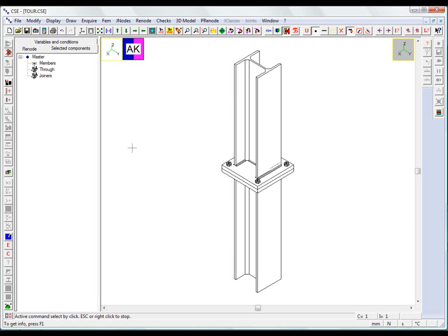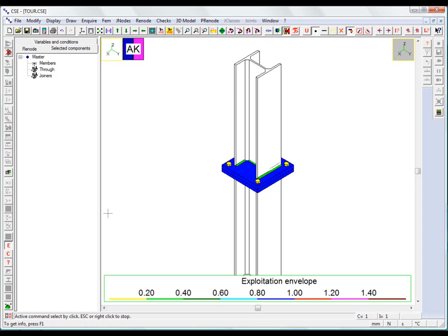One thing we can do is compare the plate checked using the FEM model and the one that underwent the bearing surface check. The maximum utilization given by the bearing surface check is comparable to that from the analysis of a sophisticated FEM model that includes the state of stress in the plate, based on the forces transmitted by the bolts, the welds, and the bearing surface. Let's look at the current results.